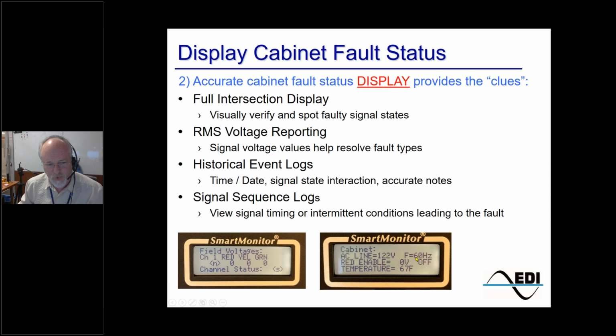This should not be any 5 hertz either way. So 65, 55, that's where you should see it. 99% of the time it's going to stay at 60. But if you start seeing something other than 60, you've got to start thinking there's something wrong with your service.